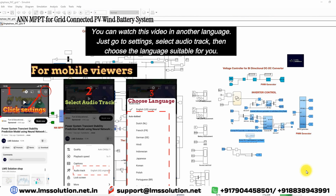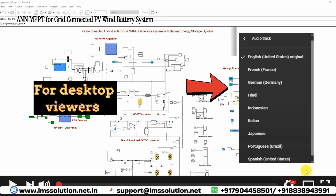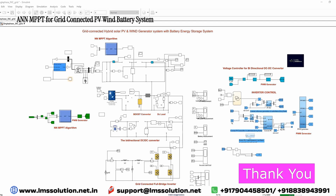Today we are going to see about the neural network MPPT controlled grid connected PV wind battery system, also known as a hybrid DC and AC microgrid. This hybrid DC and AC microgrid will be controlled by means of neural network MPPT in the wind energy conversion system as well as the solar PV system, and the DC bus voltage will be controlled by the voltage control method in the bidirectional converter of the battery, and the current control is applied in the grid side inverter based upon the SOC of the battery and PV power.